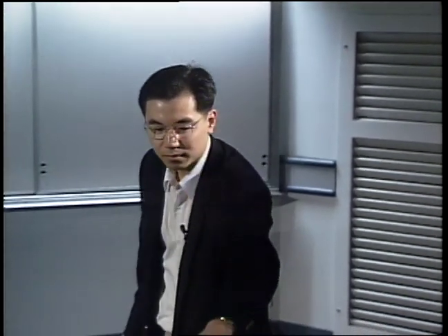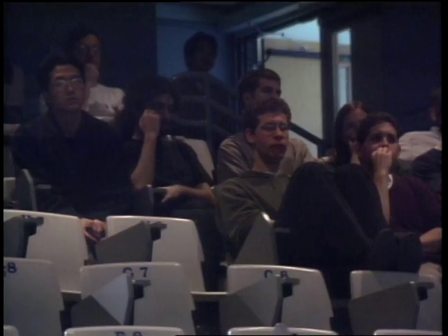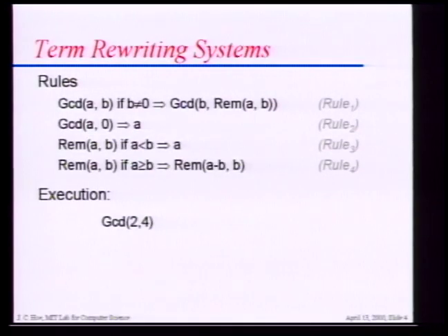So in the framework that I'll talk about today, we're going to basically bypass all this translation and synthesize directly from an operation-centric description. So in the framework that I'll present, we're going to describe hardware design as term rewriting systems, or TRS. So TRS is a very well understood formalism that has been used quite extensively to give the operational semantics of programming languages. Informally, a term rewriting system is made up of a collection of rules.